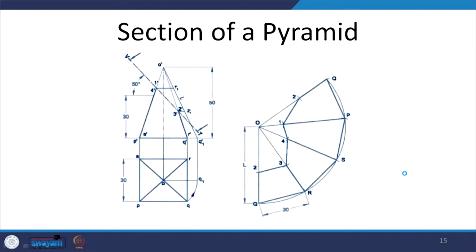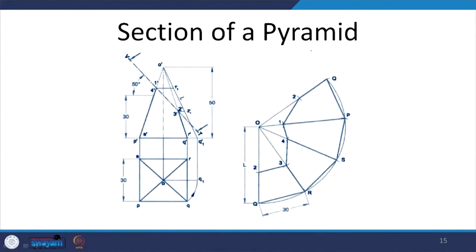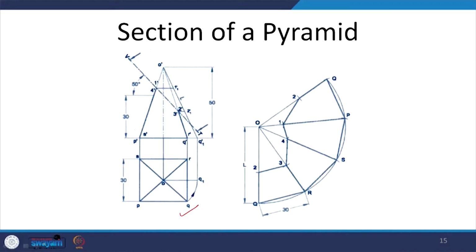So it is exactly the same process, which is a little complicated and difficult in case of a cylinder or a cone, but in case it is a polygonal pyramid with a polygonal base, we will have it much simpler. Suppose this is a square base pyramid. We very clearly know that we have these four slant edges, and the heights of these edges are now marked here.